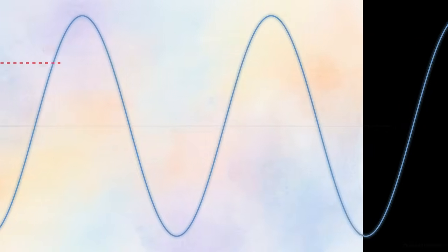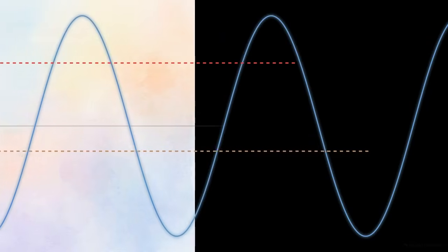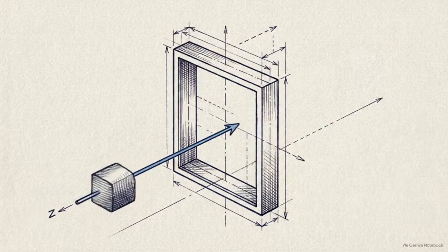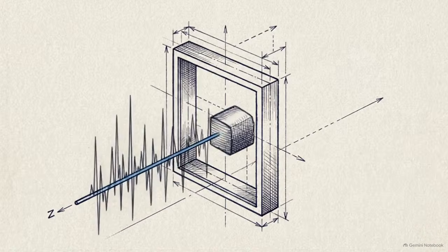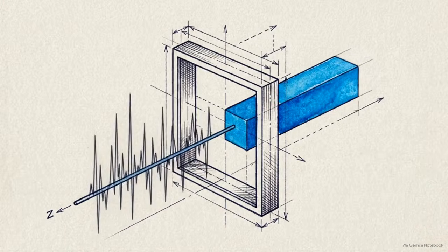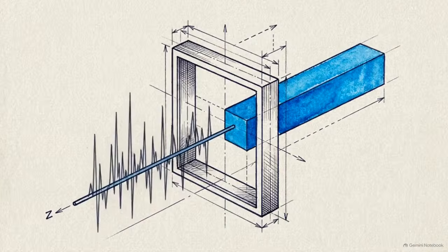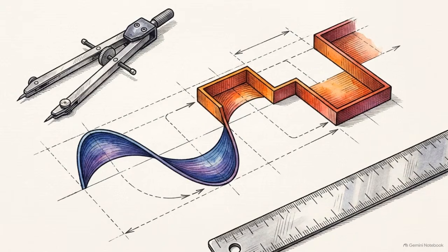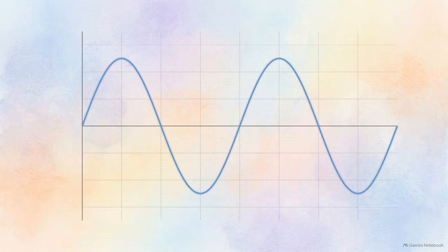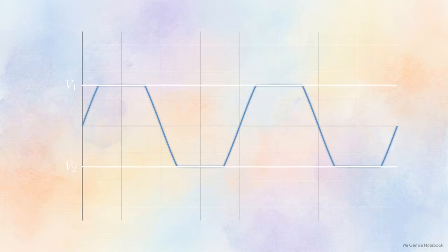An engineer can set the positive ceiling at 5 volts and the negative floor at -2 volts, customizing the exact shape of the output. Combining these two opposing boundaries creates an impenetrable envelope, ensuring the downstream system receives perfectly processed, safe signals. This process serves a dual purpose. Beyond protecting hardware, it acts as a tool for synthesizing entirely new electrical shapes. We've taken a smooth, sloping analog wave and mechanically forced it to mimic a blocky, angular pattern.